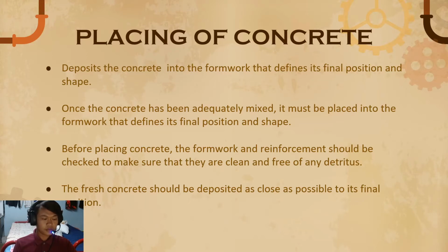Point 3, before placing concrete, the formwork and reinforcement should be checked to make sure that they are clean and free of any detritus.